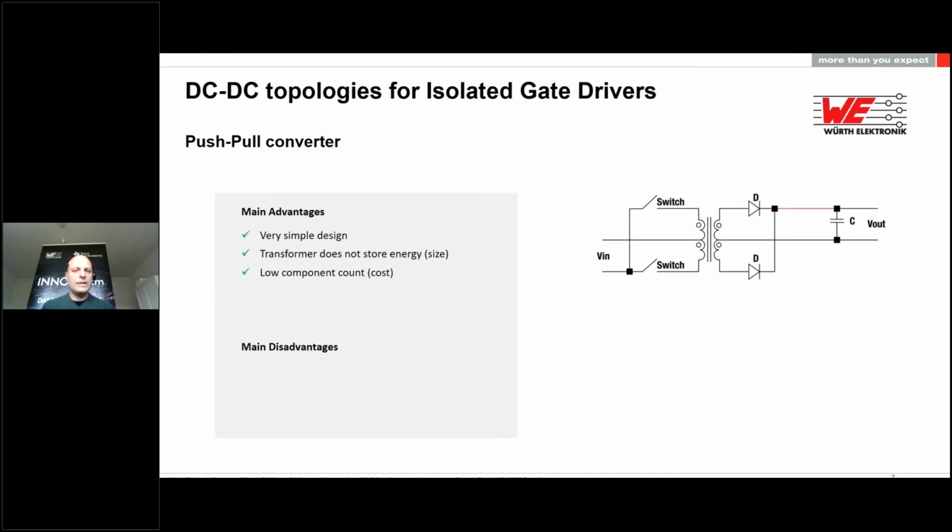There are very few components, like 2 low-side switch devices on the primary that can be easily integrated in the controller IC, output rectification diodes, and a capacitor. Again, there is no output inductor and no feedback loop components. There is no need for a snubber due to the very low energy storage in the leakage inductance. With this topology, we reach an efficiency of around 85 to 92%, but of course, there might be other losses involved, like linear pre-regulation or post-regulation, and losses due to voltage doubler rectification stages.